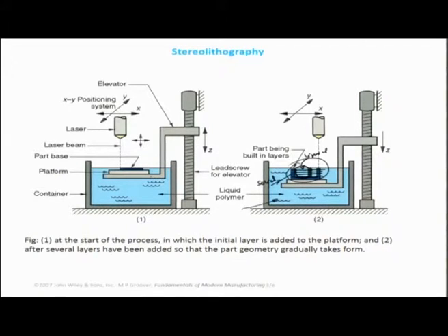So, the curing action would only happen here, and the laser would be switched off while it scans this portion, again off in this area, and whenever the laser is switched off, there is liquid resist left over, and when it is switched on, there is solid resist left over, and layer by layer this way you can fabricate the parts.